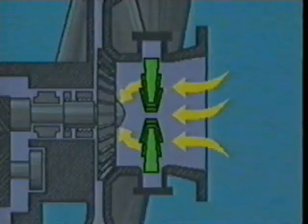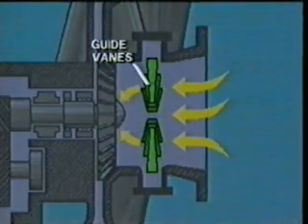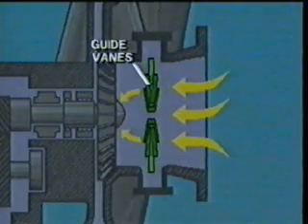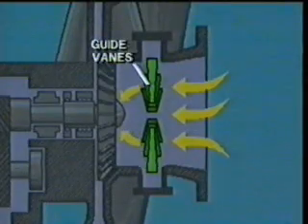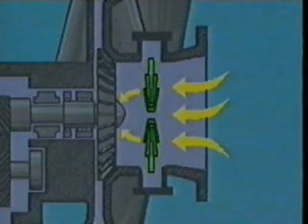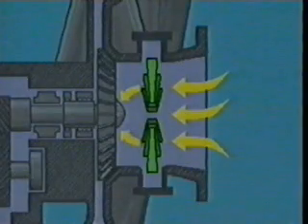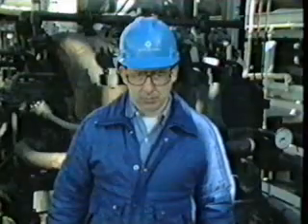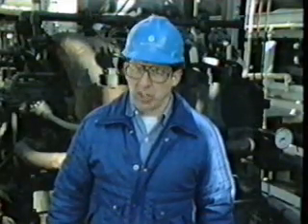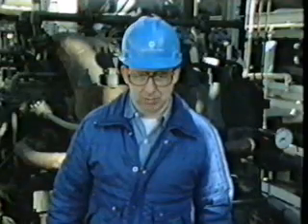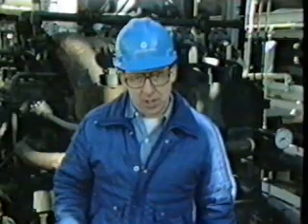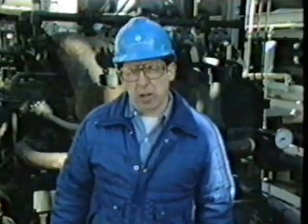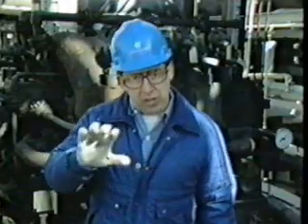To control performance in some compressors, adjustable guide vanes are installed just ahead of the impeller. These guide vanes slightly throttle the suction gas flow and pre-rotate the gas into the impeller eye. These guide vanes can either be adjusted manually or adjusted automatically with a suction pressure controller. One problem in dealing with gas flow through a centrifugal compressor is surging. Surging is a rapid flow of gas back and forth within the compressor. It is an aerodynamic condition caused by a recirculation of the gas starting near the edge of the impeller.